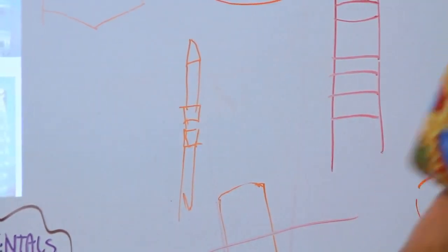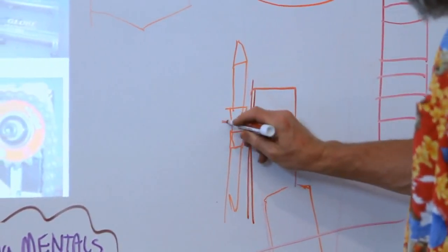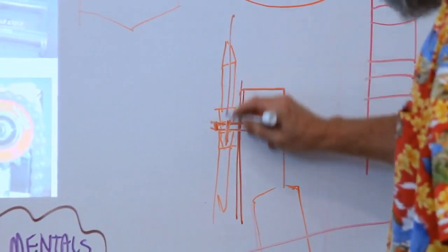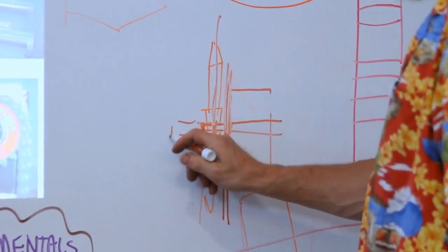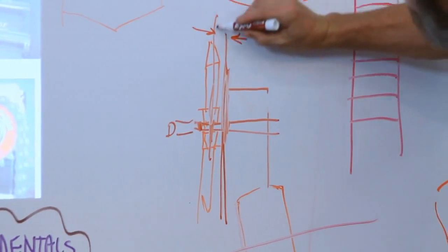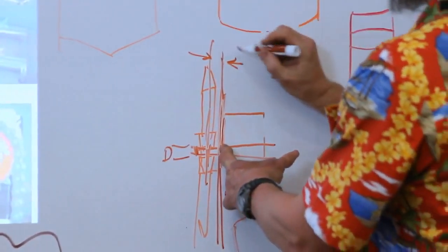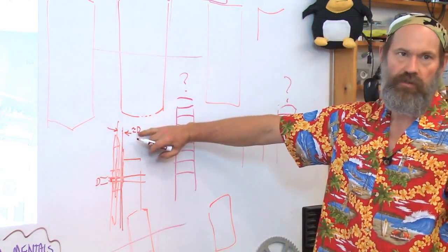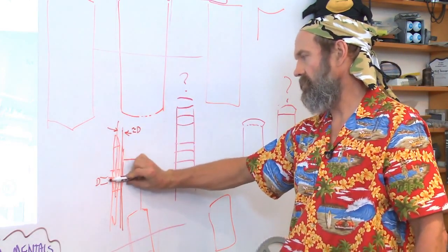And then I have another structure here with a bolt passing through, from the center of force here to where the bolt, this is D. I can typically get this center distance from the center of the chain force to the face of the structure, which is where the bolt is first attached, to be on the order of D itself. So the forces from the chain are not dominating bending of the bolt.